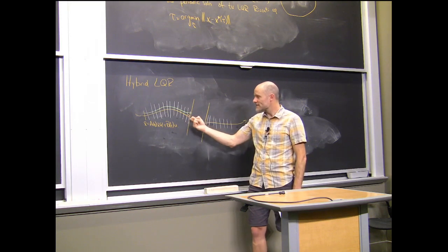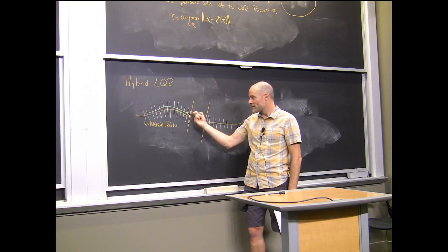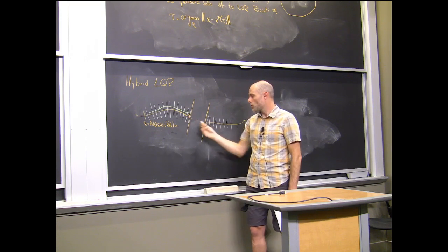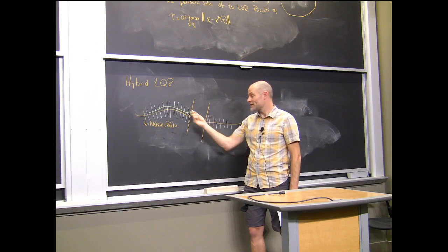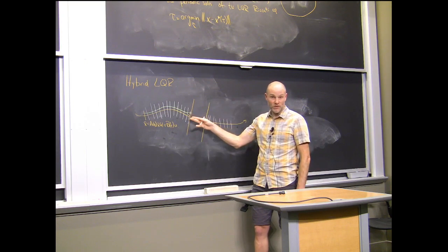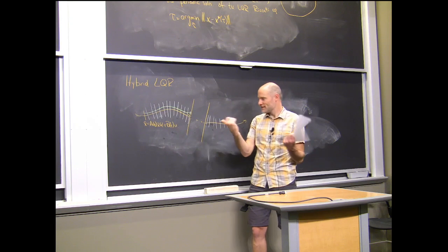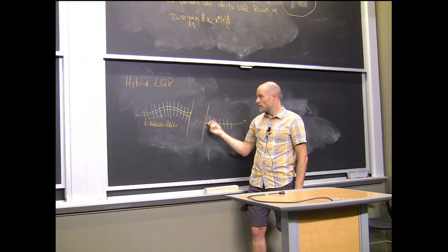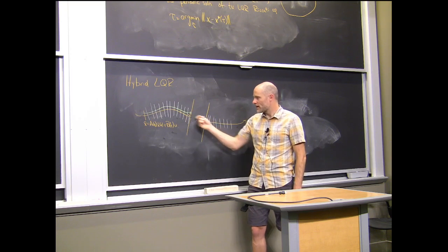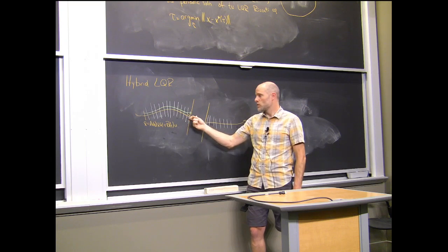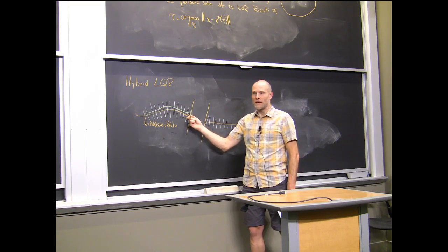In practice, even that depends on knowing and estimating the state of the robot, and that can be sensitive. So there's a lot of work to try to make those gains go. I mean, intuitively, what you want to do is have those gains almost go to zero if the goal is to go in the opposite directions on either side of the impact. The formal way to achieve that is to talk about robustness with respect to the uncertainty in your state estimate or uncertainty in the guard position, which will then drive the gains to be zero in an optimal control design.